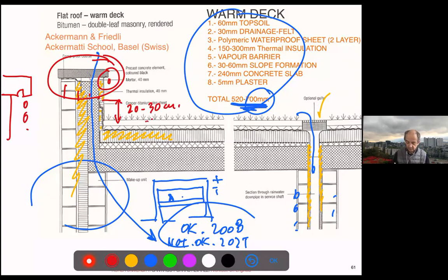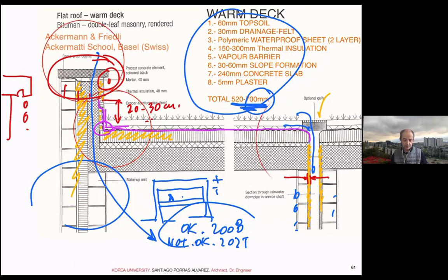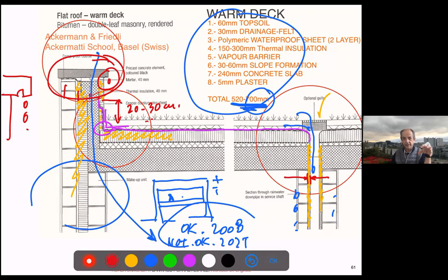And you will need always to have some continuity of the waterproof. So you will need a duplicate waterproof on those connection points and make sure it is continuous until the water slides. So the water will not accumulate and will go out always, right? See always also this gap we have between the pipe and the walls. It's not offering insulation, but also because things need to move independently, so the pipe will not crack. Well, these are important points. And usually it's the 3 points you have to detail always.